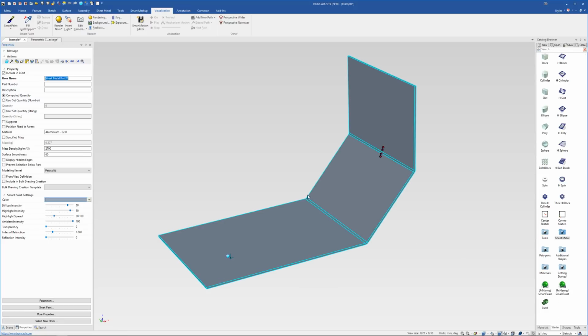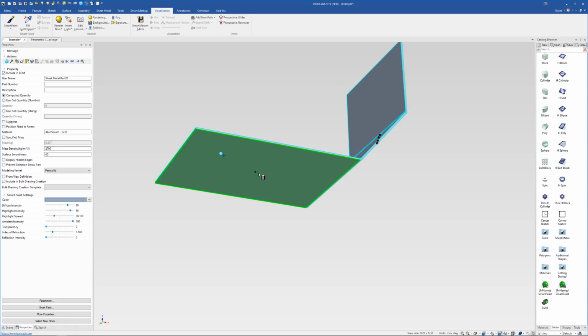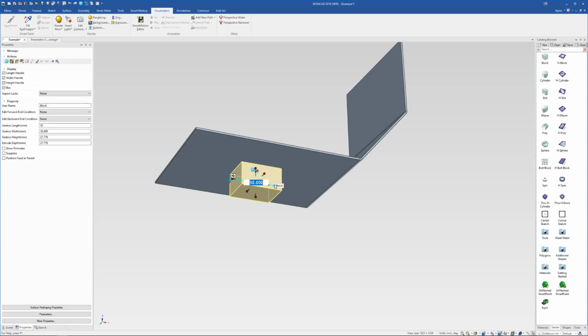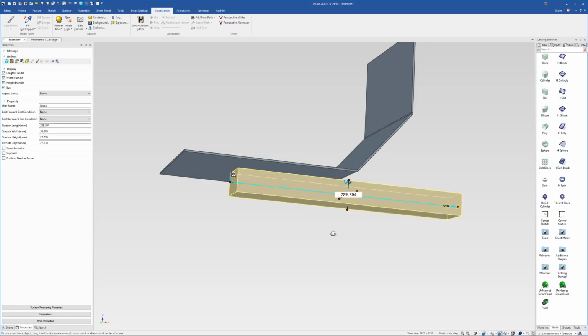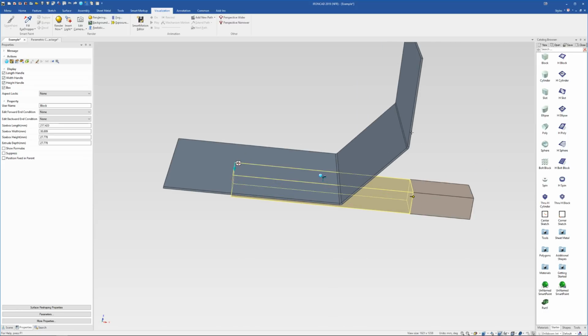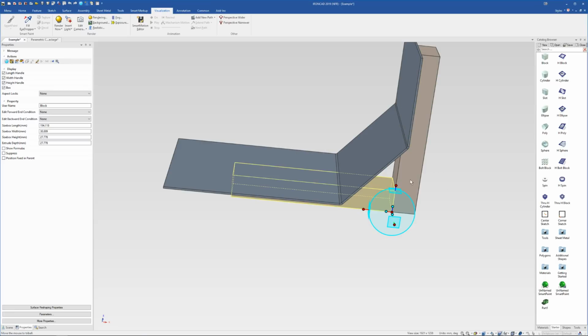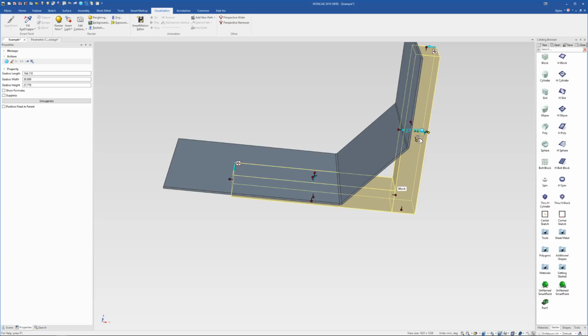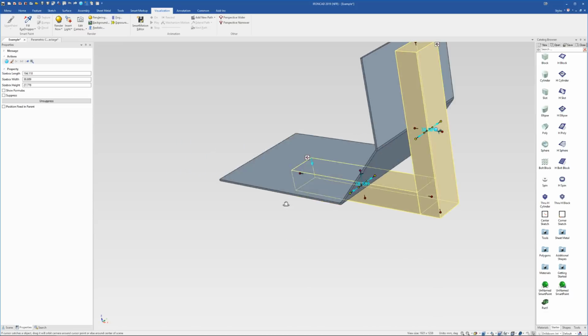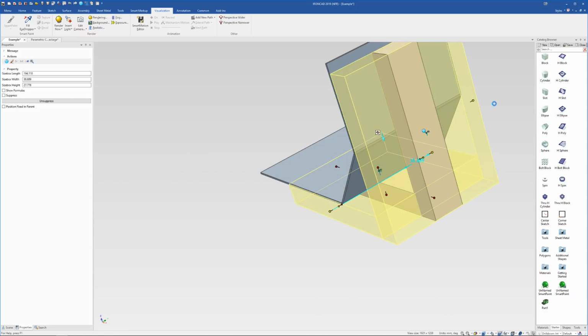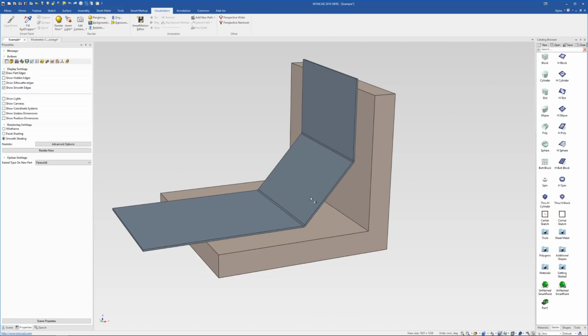So I'll show you what I mean with a little bit of reference geometry for where this type of problem might occur. Let's drop out a new part and stretch this part out over to here. And then I'll copy the IntelliShape actually, 90 degrees. And we'll then just resize this across. So this is kind of our fake wall.